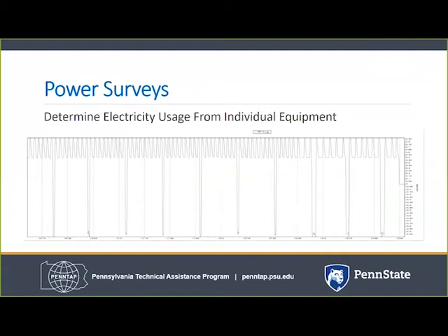We can add much more detail to this picture using power logging equipment. These tools can provide high-resolution measurements of energy consumption over short intervals, for example, from every second to every 20 minutes. These measurements could be taken either for individual pieces of equipment or an entire facility. This data can reveal short-term trends in demand, such as the difference between daytime and nighttime consumption, or weekday and weekend consumption. Unexpected loads during non-business hours could reveal opportunities for energy savings.